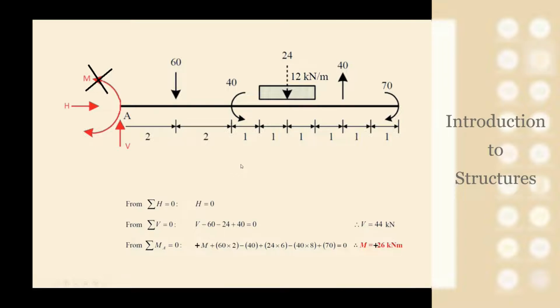This is important because, of course, after the calculation of the reactions, we need to produce the shear force diagram, the axial force diagram, and the bending moment diagram. And if you have the wrong directions for your moments and reactions, the diagrams will be wrong as well, because the diagrams have signs as well.